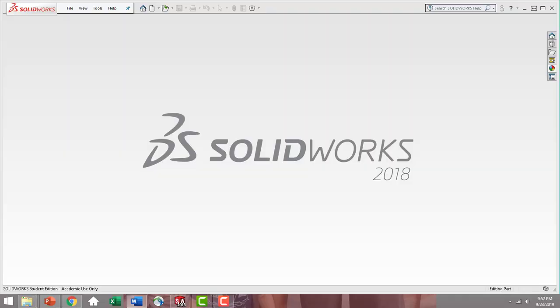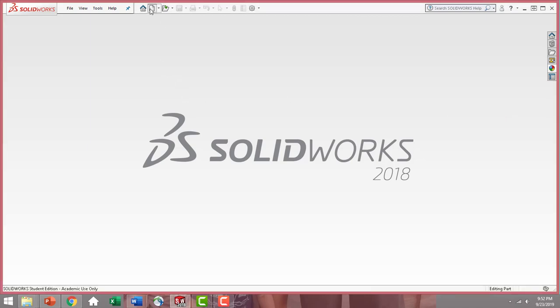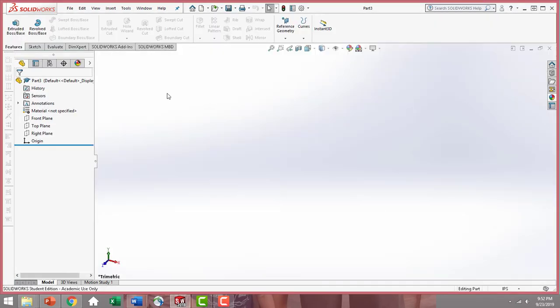Hey everyone! Now that you've created your skinny brick and all your configurations, it's time to move on to creating your derived parts for your Milestone 2. This video focuses on the derived parts for the helicopter project, so if that's not your project, look for the other videos made. So to begin, we're going to go to New, select Part.